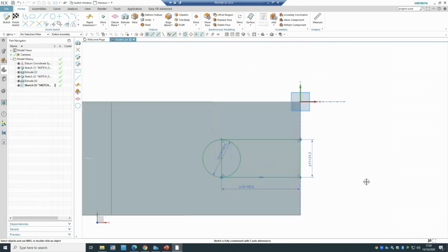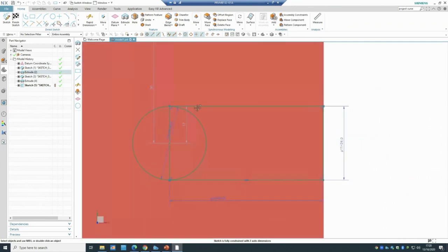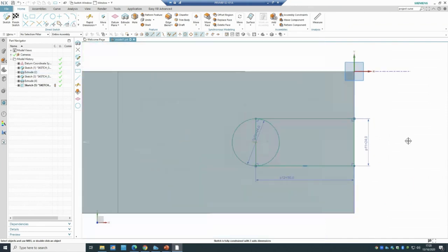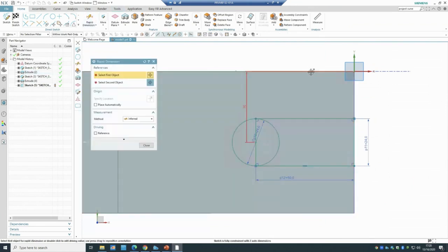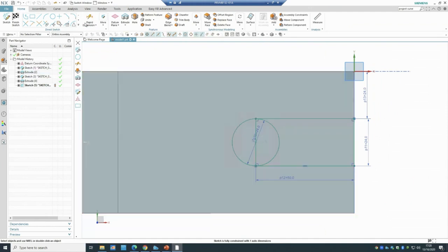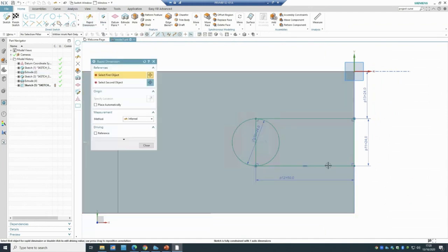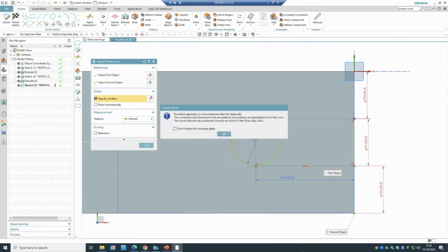And you can see these are perpendicular, this one is perpendicular, they're all connected on top of each other, and I have to just position this one. And what I know, that length, the distance between those two based on what the drawing tells me is 24. And this one is 24. That's it. I don't need to give this one because if I do the dimensioning for this one to this one, I technically become over-dimensional, over-defined. Do you see that? It's there.